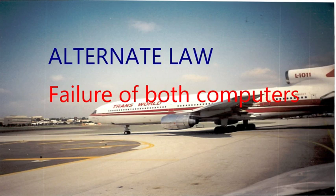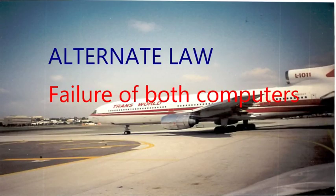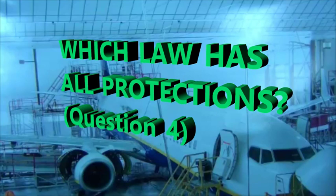When you look at the laws in alternate law, there could be some variation as to how it's defined, depending on whether there's one sensor that's failing or more than one. So just keep that in mind. It's not a hard and fast rule, but do know for test purposes that normal law is complete protection. Alternate law is not complete protection. It just allows for some protection.